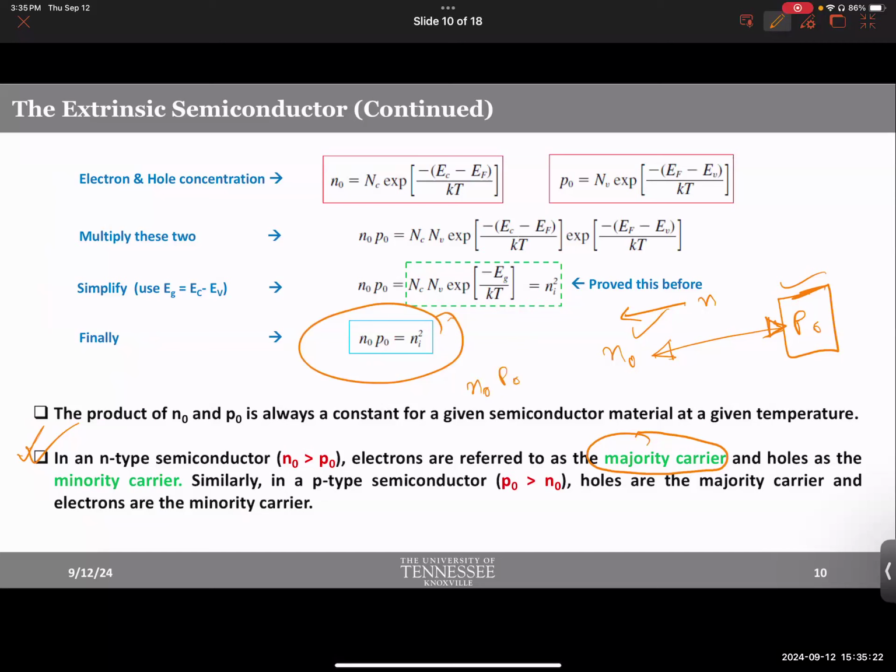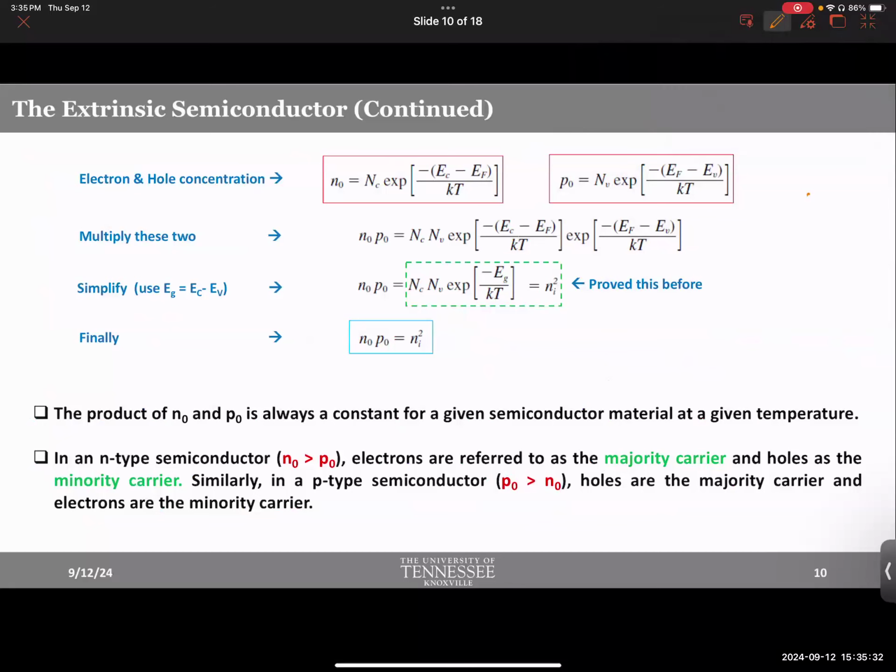And there is a fundamental limit, as you see. You cannot just get any number of electrons and holes in a system. Like, okay, I want this many electrons and that many holes. No, you cannot have it. They will adjust each other. We use the term annihilation because an electron can always pair up with a hole and annihilate each other. So they will basically annihilate each other to keep this equation fixed. So just to satisfy this equation, some electrons will pair up with holes and they will both be gone. So this is how significant this equation is.